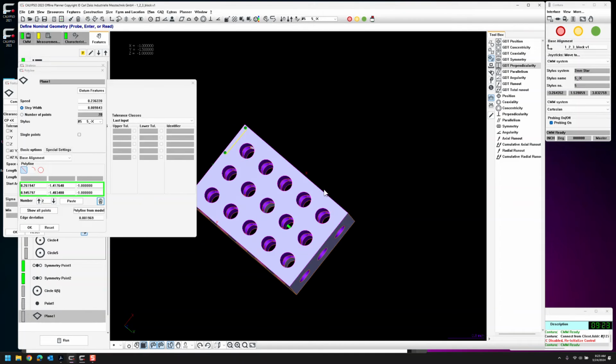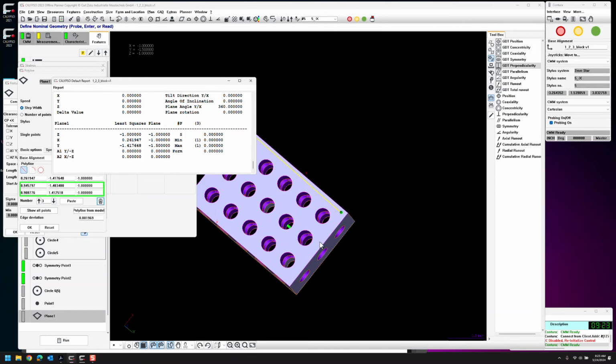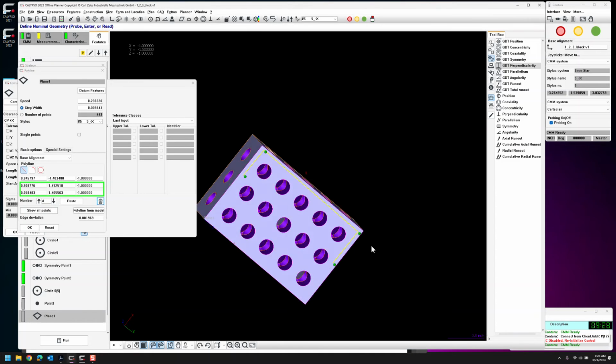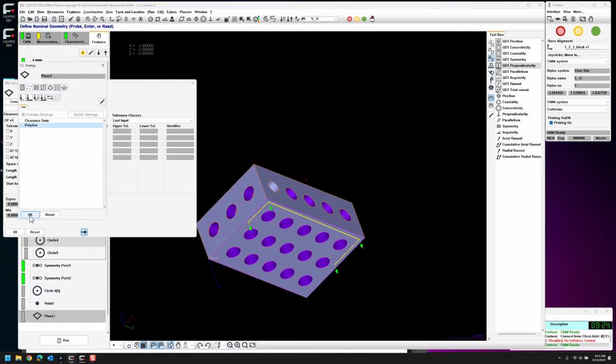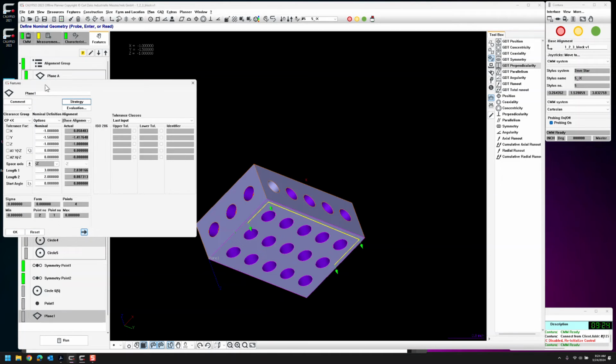And let's go ahead and come over to here, and here. So I think that that's just a nice little bit across there. I maybe could get across there too, but maybe I have a post here. So I'm just going to go around the edge. Speed 236 is fine. Step width 10 thou is what I want. Remember 0.25 or 10 thou. Click OK, click OK. I'm going to rename this just for my convenience.